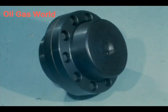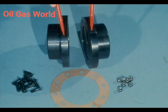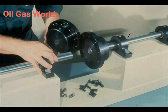The other type of rigid coupling we want you to become familiar with is probably the most basic type. This is a flange coupling. It is very simply constructed and quite easy to understand. These are the hubs of the couplings. And these are the flanges. The coupling halves are installed on both shafts to be connected.